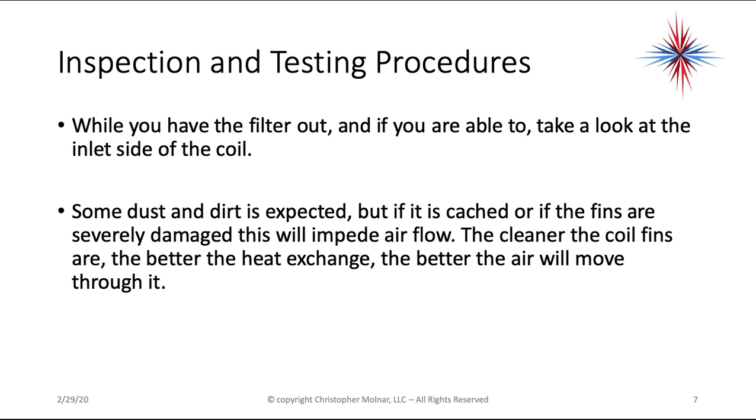While you have the filter out, if you're able to, take a look at the inlet side of the coil. Nine out of 10 times that filter is going to be sitting next to the coil or under the coil. Okay. Some dust and dirt is expected, but if it's caked or if the fins are severely damaged, this will also impede airflow. The cleaner the coil fins are, the better the heat exchange, the better the air will move through it.